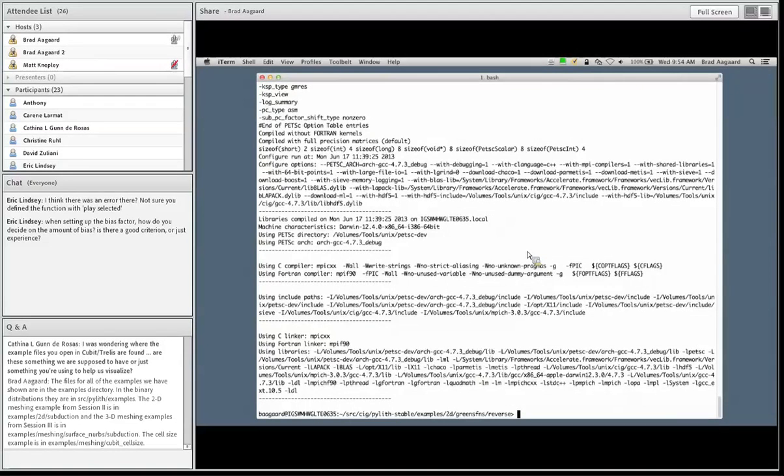By using a Green's functions problem type, it'll look for the greensfns.cfg file. That's where all our parameters are, so we don't have to actually tell it to read in the pylithapp and greensfns.cfg files. Both of them will be read in automatically.